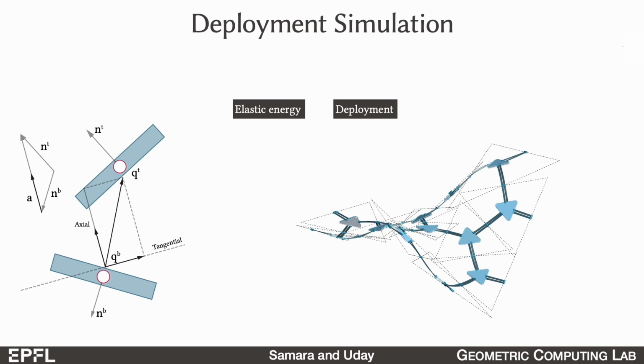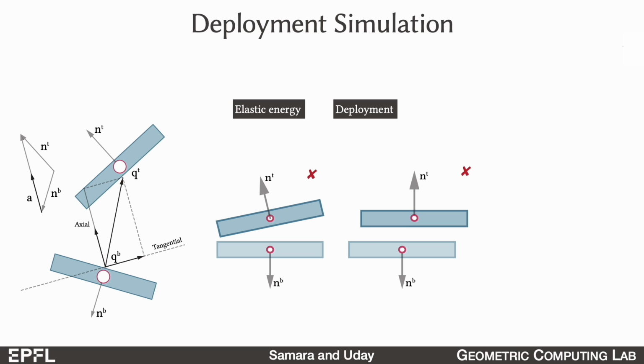Here is a 2D side view of the linear actuator. The blue rectangles are the top and bottom plates. If we simply use a linear spring to drive the plates closer, the spring will be unstable under compression and also risk pushing the plates to an inverted zero-energy state. Instead, our linear actuator will enforce the alignment of the plates' normal in addition to the distance between the plates. Our design optimization can later tune the forces applied by the virtual actuators so they are realizable in the physical models.